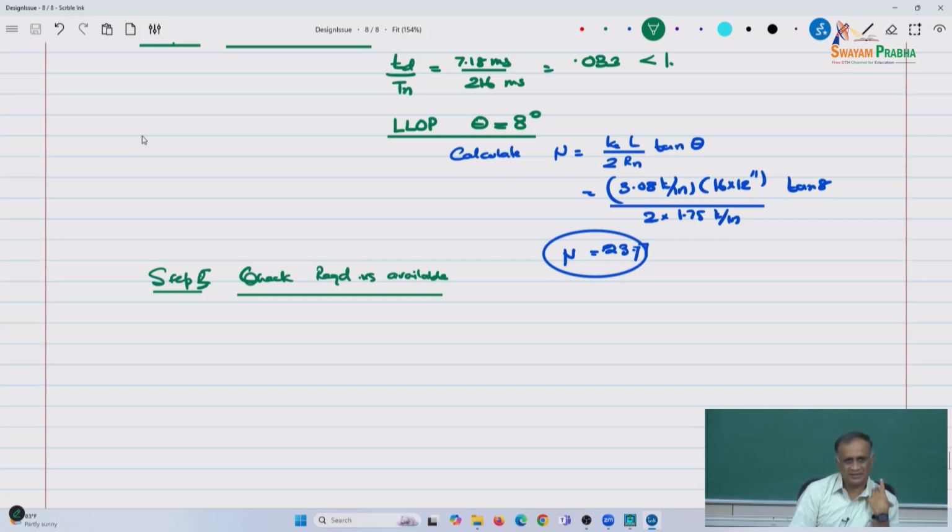We haven't addressed connection issues even in our steel and concrete. In concrete, especially at the corners, in cantilevers or any edges, you'll have an L shape. Now, when you blow out from inside, we are assuming a fixed support, but what's going to happen to that L section? It opens up. So that's actually not good.